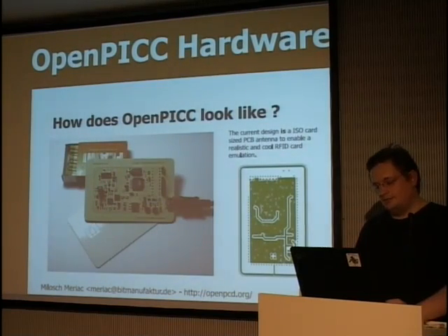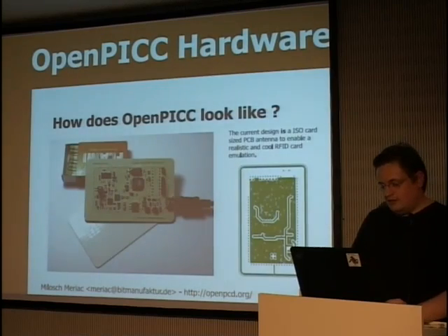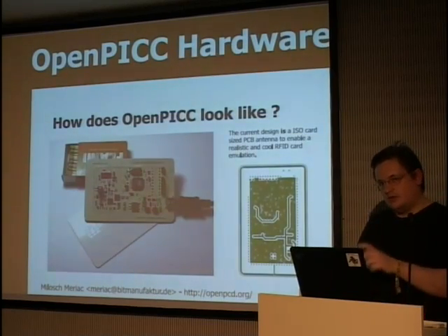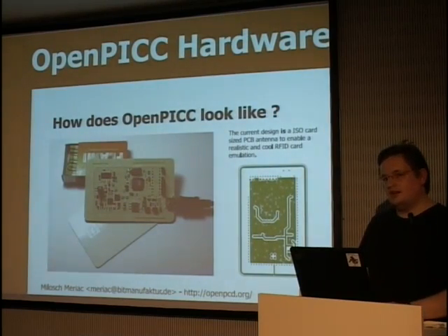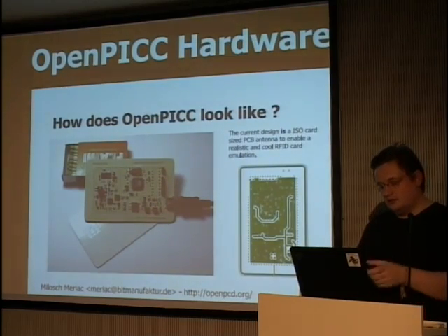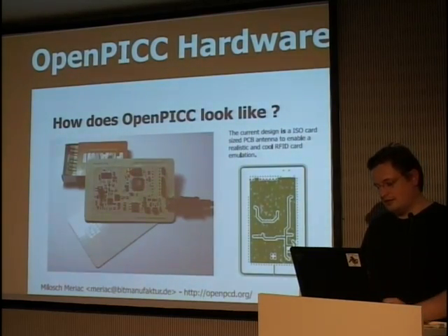So there are possibilities, and if you're interested, we can point you afterwards to places where you can get such JTAG adapters freely. There are open source projects around this, so there is a possibility to get them at reasonable pricing. But you have the same concept, the debug interface. You can do your printf stuff again, and for higher level stuff, you can easily use it as a self-contained device.